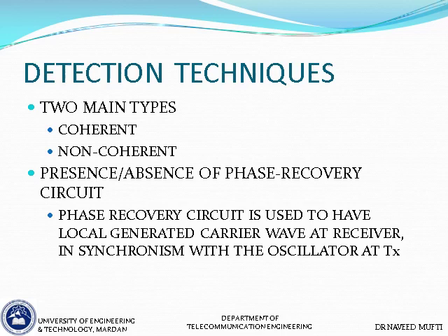So there is some piece of hardware at the receiver which tries to detect the phase of the incoming signal, and the idea is that it wants to match or lock the phase of the incoming signal with the local oscillator in order to achieve synchronization with the oscillator at the transmitter. So that's a major difference between these two types of detection.